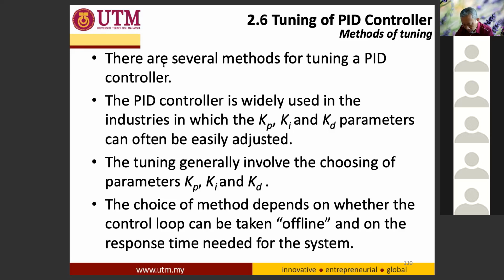Even though the digital PID controller is in digital form, where you have hardware connected to the process, the important thing for the engineers is to calculate and plan accordingly to fulfill the spec design stated in the target of the control parameters. So that's why you have to choose the right KP, KI, and KD.